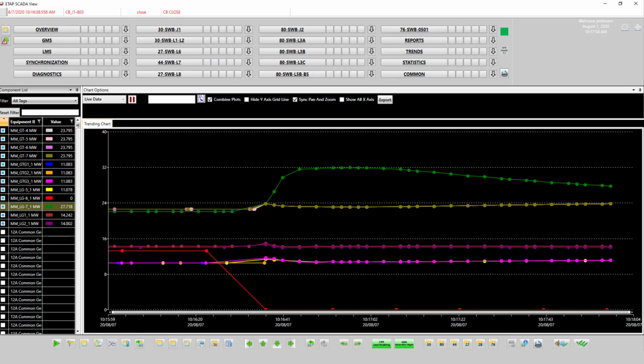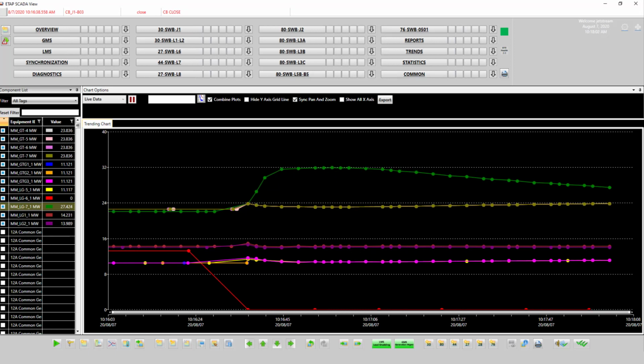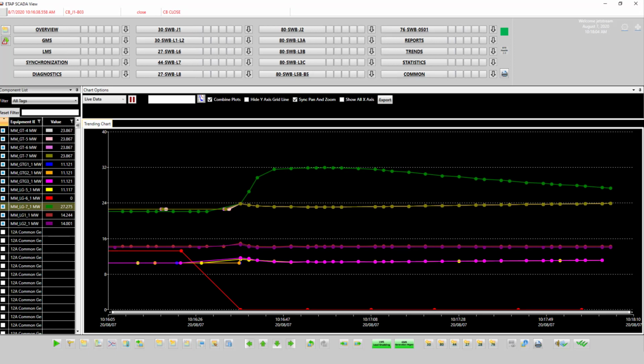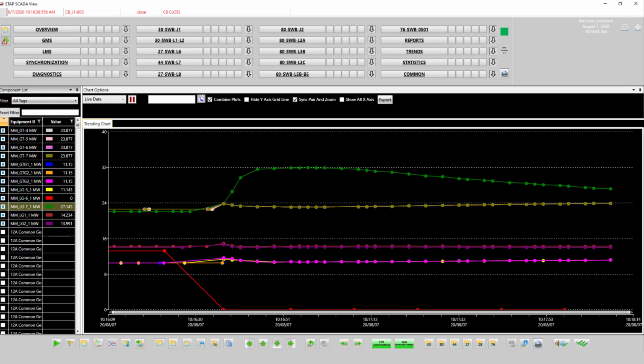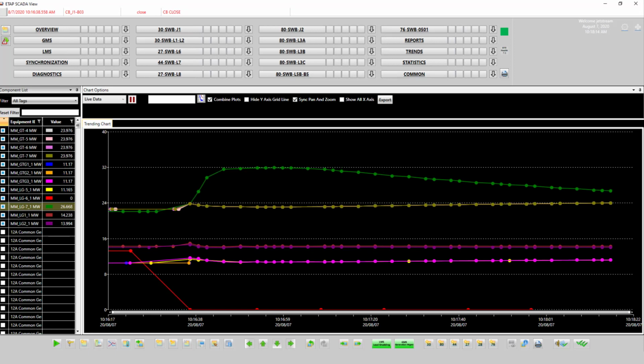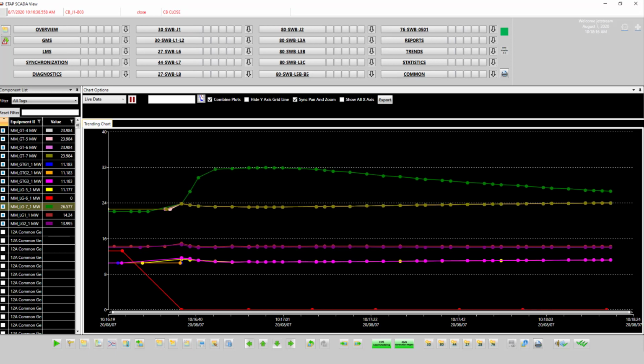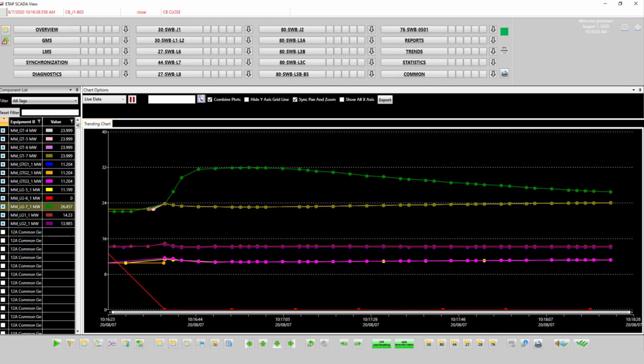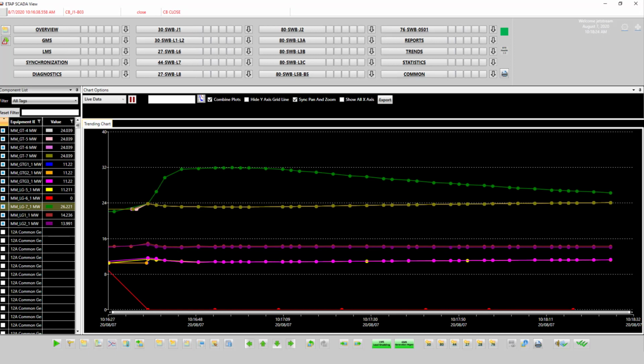This segment demonstrates the following critical capabilities. 1. The creation of custom HMIs from their existing SCADA systems to provide operators the exact look and feel they expect in the actual environment. 2. How interlocks can be configured into the system. These interlocks can prevent operators from opening or closing CBs until certain criteria are met, like generator loading, adjacent CB is open or closed, and many other conditions.